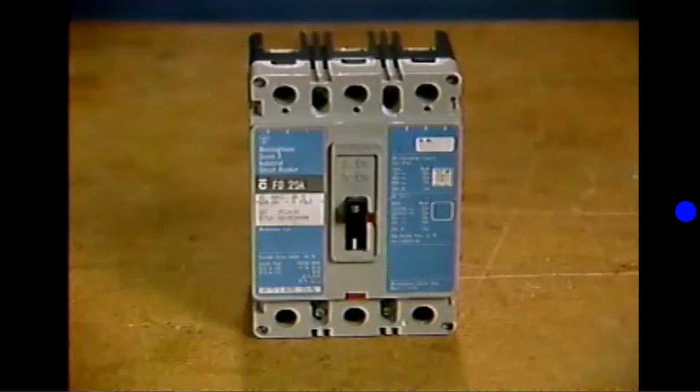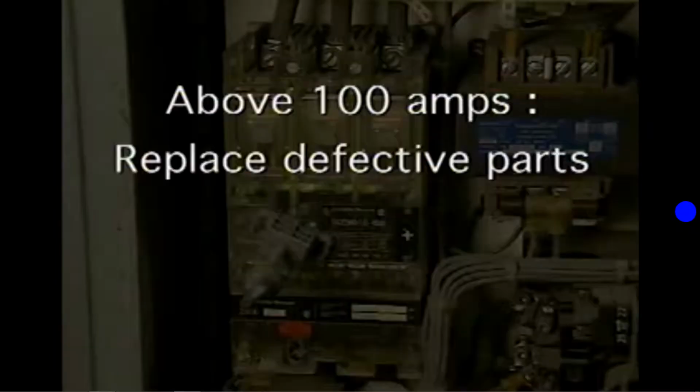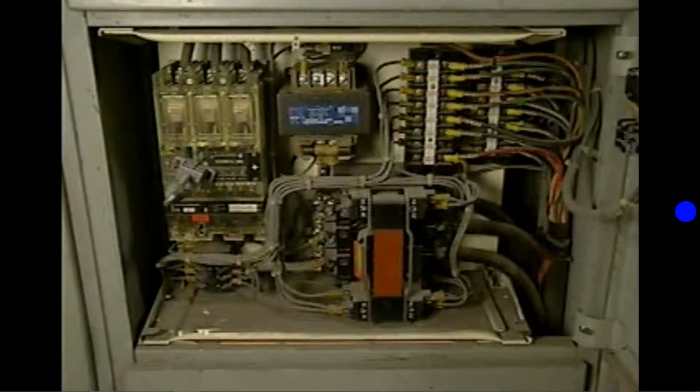If problems do occur in a molded case circuit breaker that is rated at 100 amps or below, the entire circuit breaker is usually replaced. For circuit breakers that are rated above 100 amps, the general procedure is to replace any defective parts. As we mentioned earlier, molded case circuit breakers automatically trip to provide overcurrent protection for motor branch circuits.